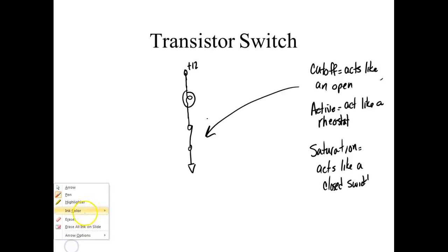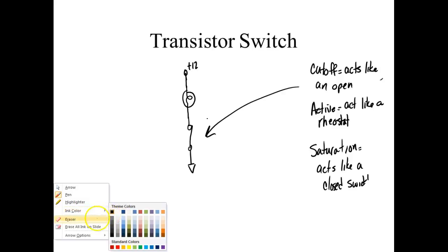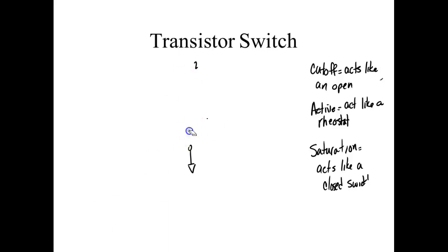The other way we can connect the load, which is the way we're going to have to look at because this is the way TTL logic works, is we're going to put a fixed resistor up here, and then I'm going to put a switch. That's my transistor. Let's say we put plus 12 volts. Then I'm going to put my light bulb over here. Of course, now it's going to be less than plus 12 volts, like 5 volts. We'd have to size these things.